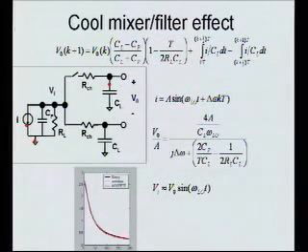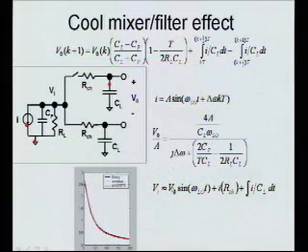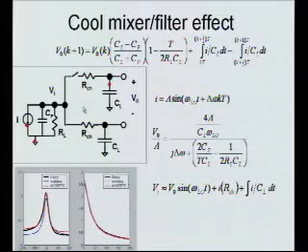The other thing that happens is that the input voltage here is continually, this node is either being shorted to one side or the other. So it essentially looks like an up-converted version of this output voltage. So you can approximate that as a sinusoidal version of it, plus some extra terms where the current coming from the LNA is dropped across the parasitic resistance of your switches and a little bit of capacitance. And if you simulate that, the approximation is just basically taking, plugging this V out into here, or you do actual transient simulations. Again, you get pretty close matching, and again, predicting this cool bandpass effect.